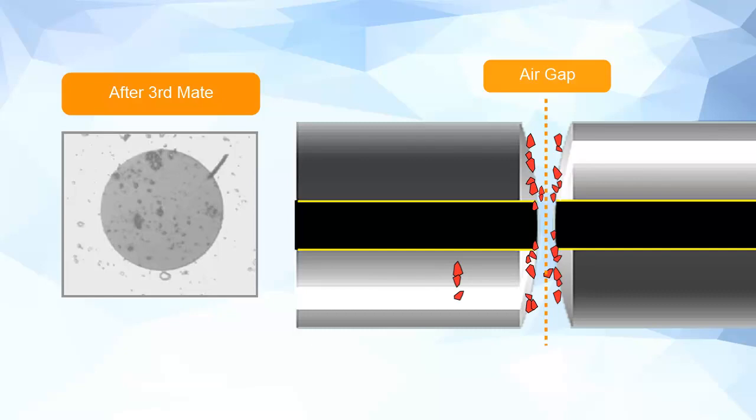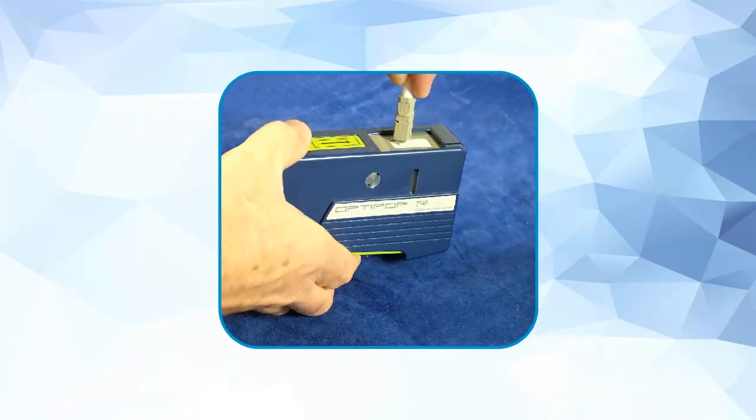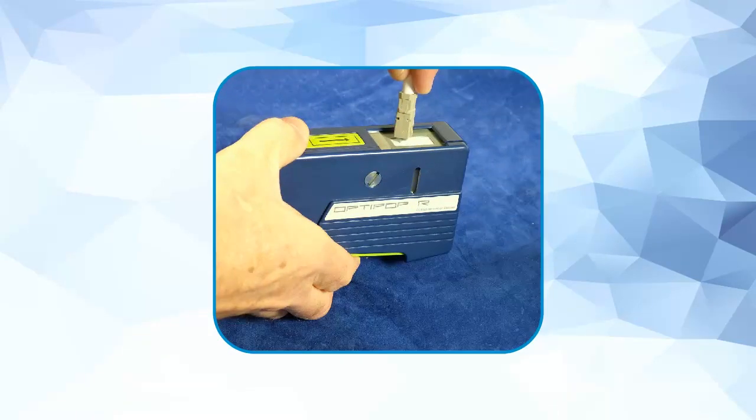Small particles tend to embed themselves into the fiber surfaces, creating damage to the connector end face. The result here is that we now have two dirty connectors, and if the connector that was being inserted was a test cord, that dirt will now be taken to the next connector that is about to be tested. Connector cleaning prior to patching is essential, and this message needs to be given to anyone involved in patching fiber equipment.